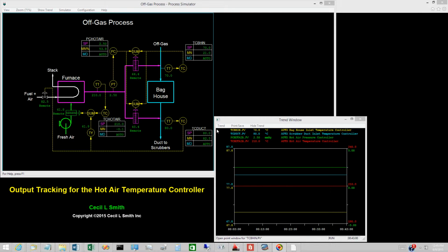This video examines output tracking for the hot air temperature controller. The hot air temperature controller outputs to a summer whose output is the fresh air damper opening. To configure output tracking, we begin by asking the same two questions as in the previous video.